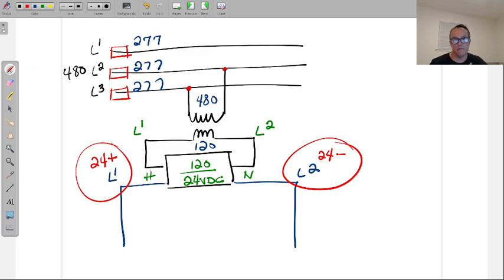Is my power supply okay? These things are very sensitive components, in fact, because they're converting AC to DC, so they get a little bit hot internally, and they're usually inside a control cabinet, which doesn't have a lot of airflow. They do have fans on the outside, but you're in an industrial area, and these fans get clogged up, and the electricians are supposed to go through and do preventive maintenance and clean up these fans and change filters. But in reality, a lot of these control panels are pretty hot internally. So that's the weak link of the whole thing.